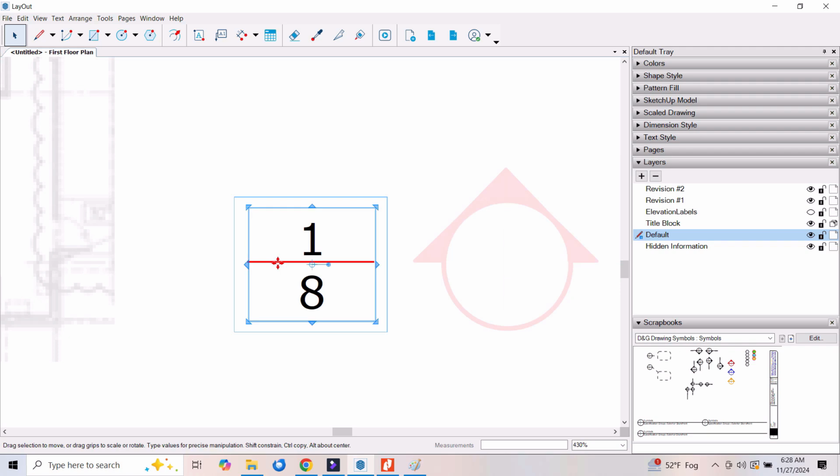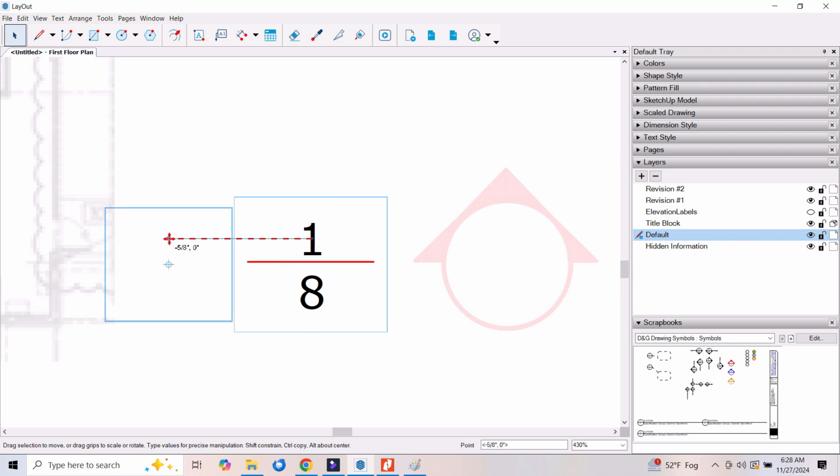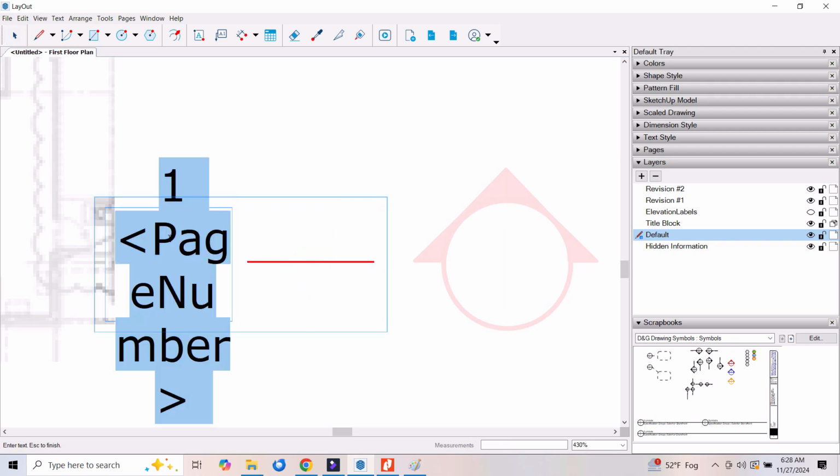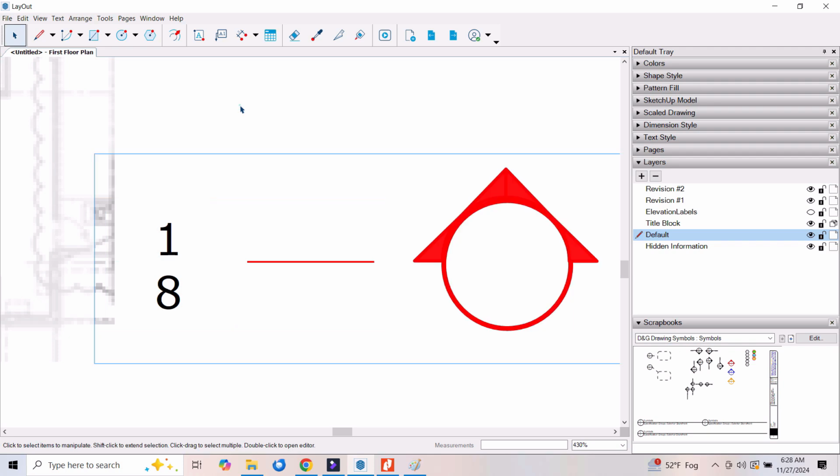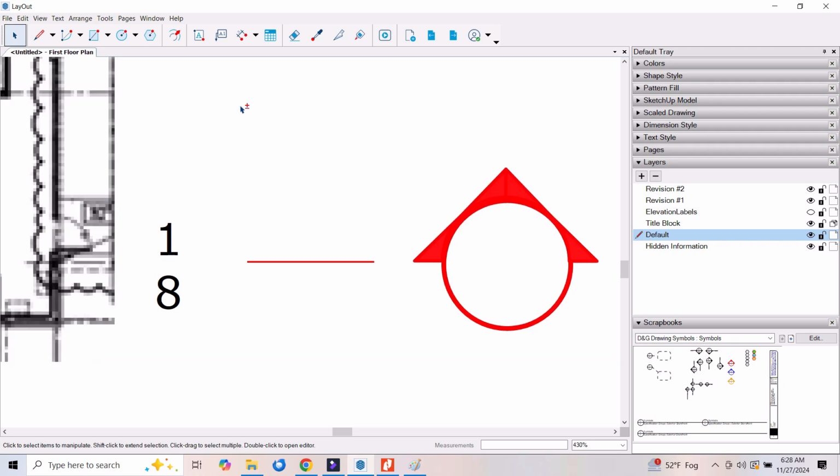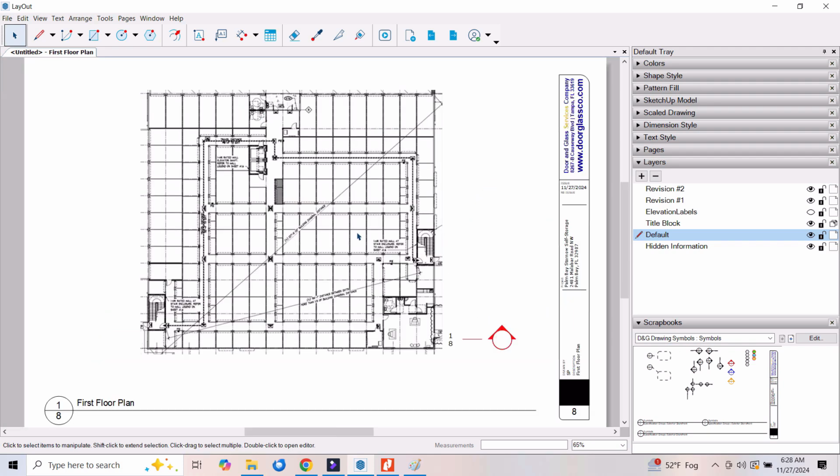Okay, this is the text box, right? And all this is the number 1, and then enter, so a new line, and then page number is the Autotext value, and that's giving us 8 because we're on the 8th page. I'm going to hit Shift Z to recenter, and then I'm going to hit Control Z to undo what I just did in moving this thing around.